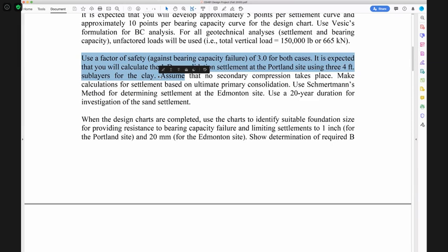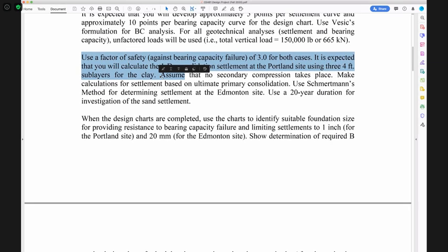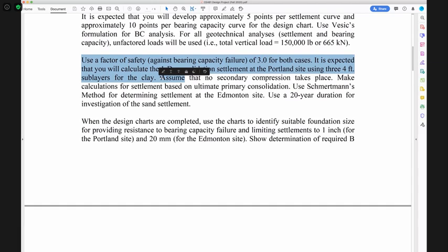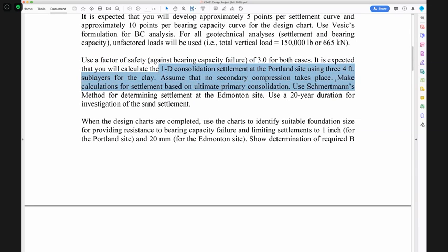And ideally, then you'd have to partner with that, soil samples and consolidation tests going to depth. In this example, we only have one value for all the consolidation material, but in principle, that's what's at hand here. We're heading towards that use of 3 layers to refine the entire analysis. You'll be refining the stress distribution, by the way. We're going to assume no secondary compression takes place, so that will not come into play.